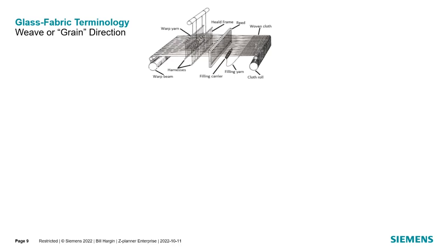The top image here, I'll show more images as I roll this out, shows a good old-fashioned loom. All the loom characteristics here have been around for hundreds of years, but today the equipment that weaves glass runs at super high speeds. The filling yarn in the cross direction is shot through with these automated machines with a high-speed air jet. If you go into a glass plant or a weaver, as they're sometimes called, you'd think you were in a room with 1,000 sewing machines running as the looms do their work, and they make you wear earplugs. It's fairly loud, actually.